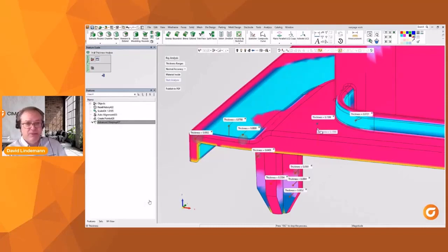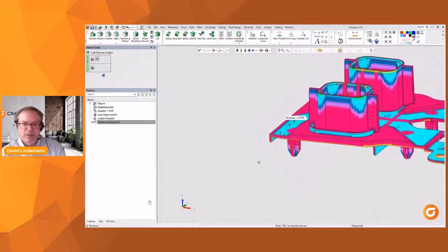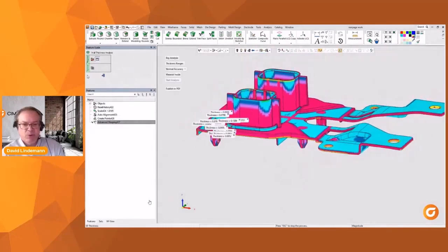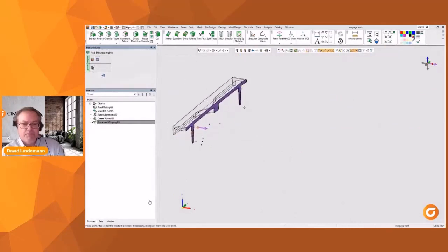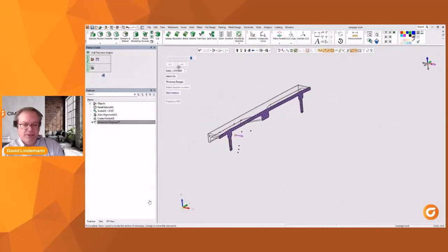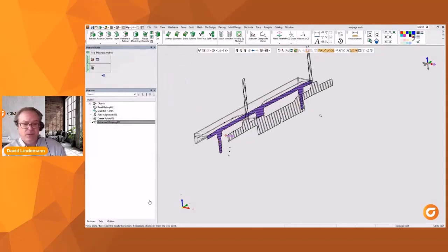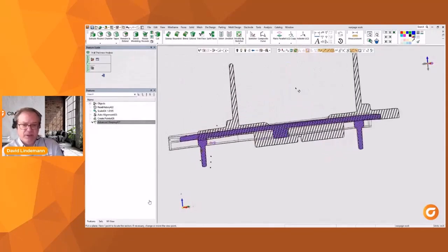If I click on the end and all the way to the other end, I've got the overall length. So I'm looking at areas in particular that I know are going to give me a measurement for the wall thickness. Right? And there I've got some important data now that I can present to the customer. Here is another great way to understand what is happening with the wall thickness. Am I consistent from front to back, from side to side? Well, we can cut this cross section.